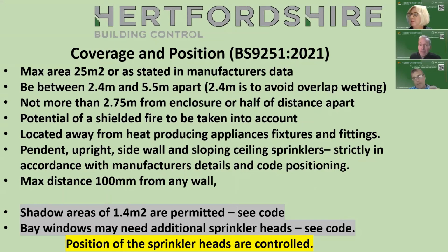at BCA level. BCA, Building Control Alliance, is a national group where private sector building control meets with public sector people like myself. When the government brought the legislation in, we told them this would be a grey area that everybody would be asking about, and they really left it to us to pick the bones out of the legislation and make decisions. The decision round the table was that yes, you do need to retrofit sprinklers to all the lower level flats if you raise the block to above 18 metres floor level.